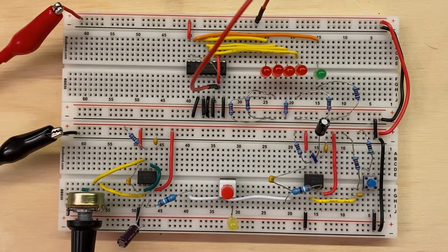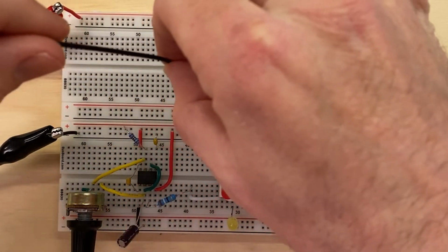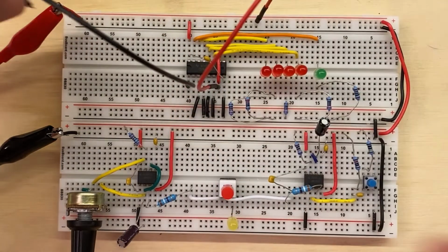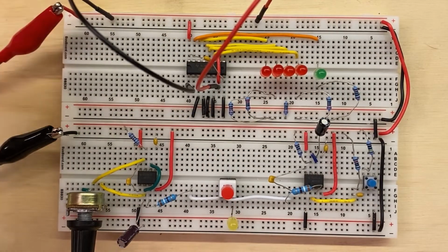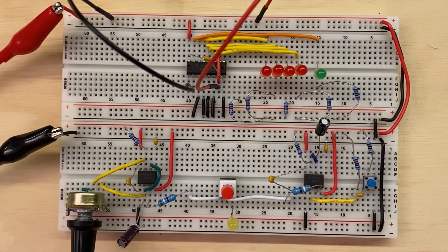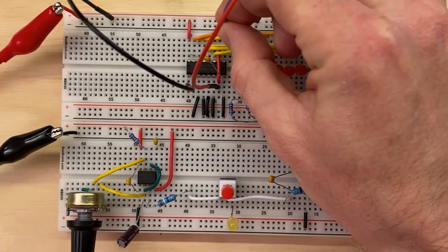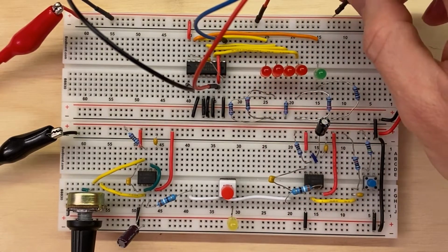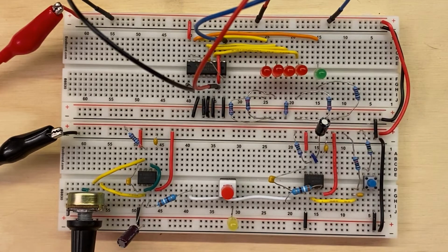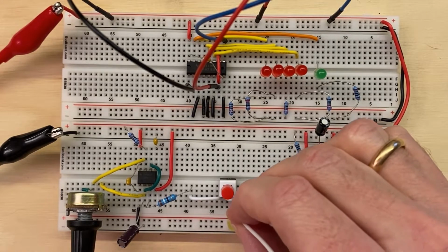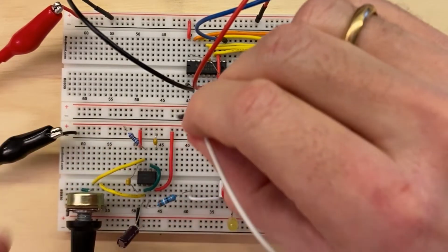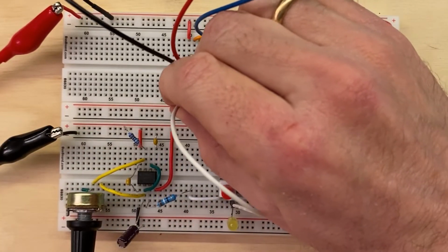Okay. We have our master reset right over here, and we have to put that to high as well because that's the active low. Right? If we want to reset the pin, we have to put it to 0 volts. We don't want to reset it yet, so we keep it high. And it's the same story for this load pin. That's active low too. We don't want to load it up. We put that to 5 volts. And of course, our clock pin. So I'm going to come here to our clock and connect it to the clock pin.